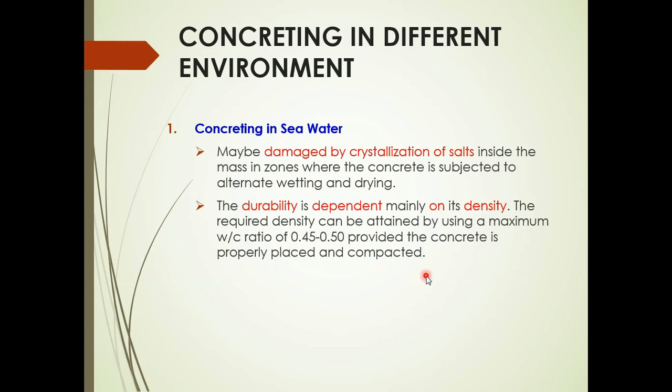The durability depends mainly on the density of the concrete. So the required density can be attained by using a maximum water-cement ratio of 0.45 to 0.5, and also by providing well compacted concrete.